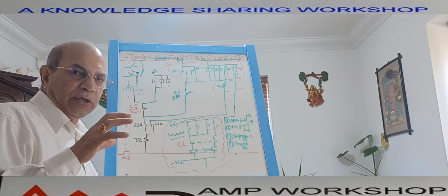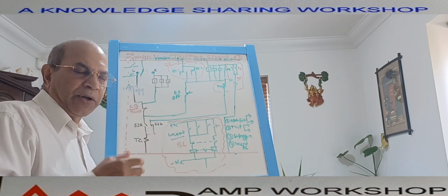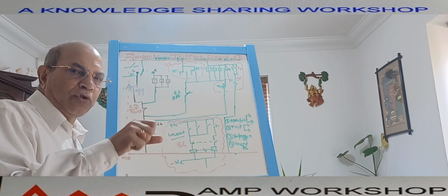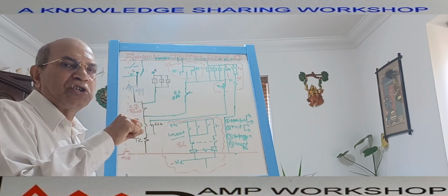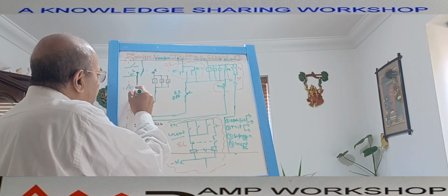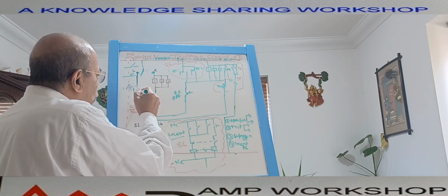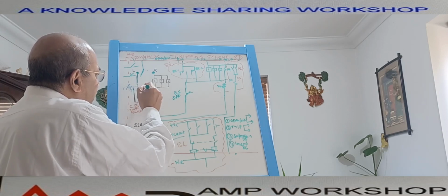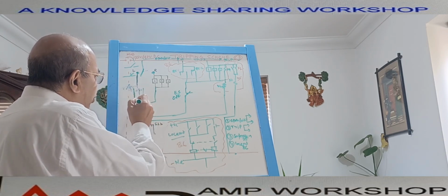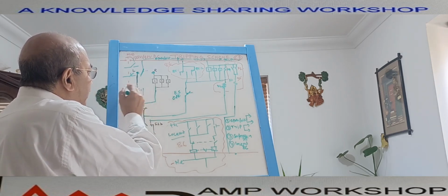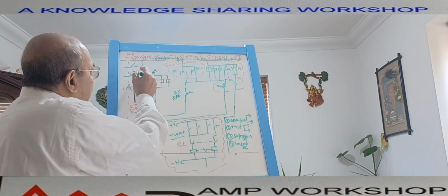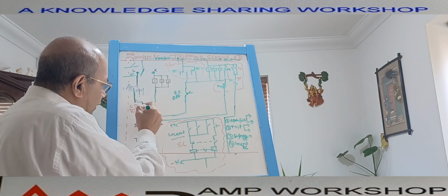If we want to open the circuit breaker, we put the switch in the open position or trip position. I have shown the three positions. This is the trip position, this is the normal neutral position, and this is the close position. As we go for the tripping operation, we select this position. That means we rotate the handle of the selector switch to the trip position. Then immediately the local trip position is selected.